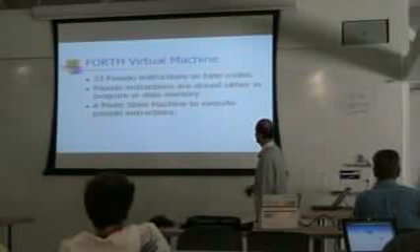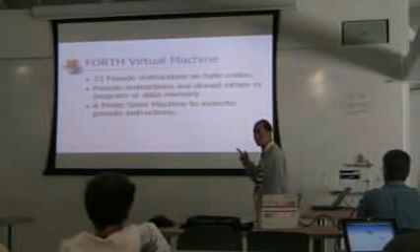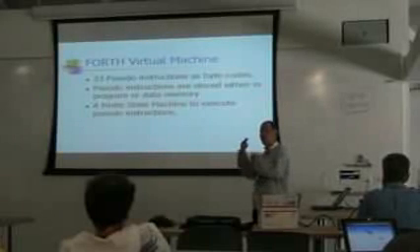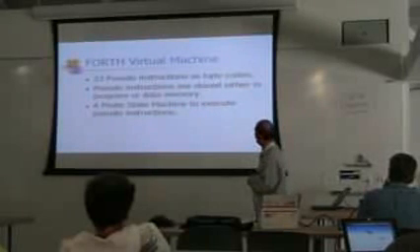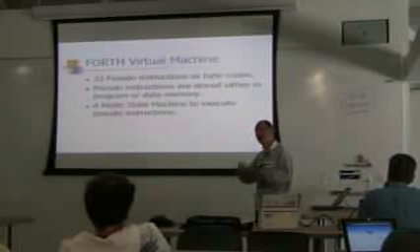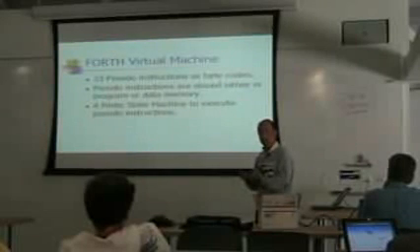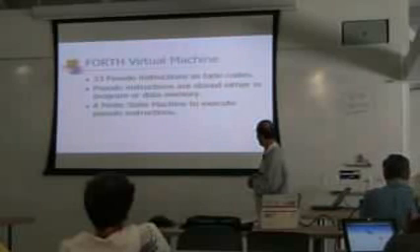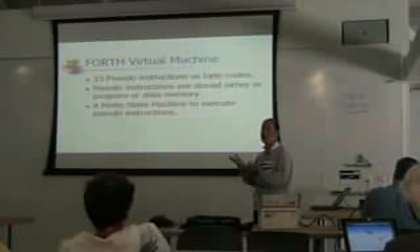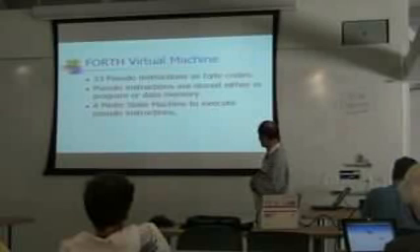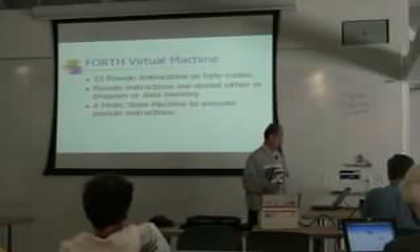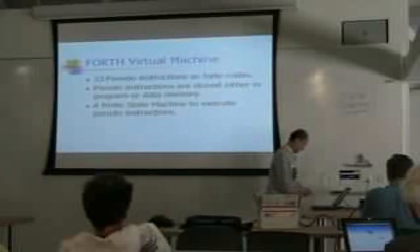Inside the eForth virtual machine, there's a finite state machine. This finite state machine will go into the memory and fetch out the pseudo instructions, execute them, and then fetch out the next one. So it's just like a real machine, but it has an instruction set you can design any way you want. With about 30 pseudo instructions, we can build a complete eForth virtual machine.